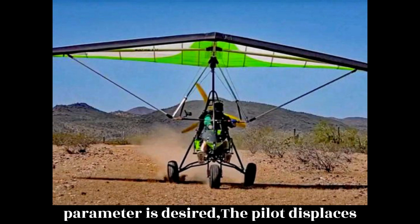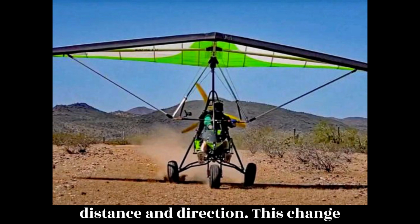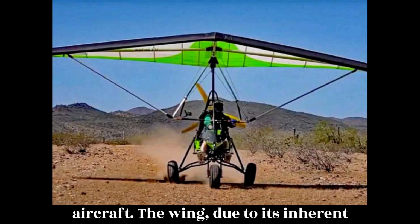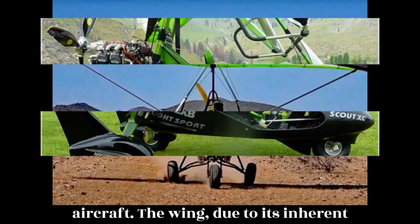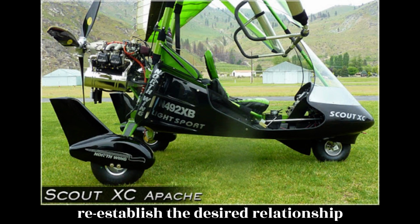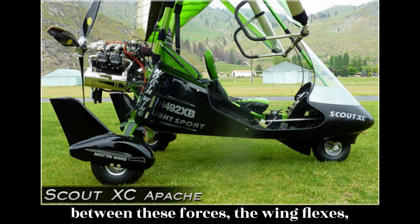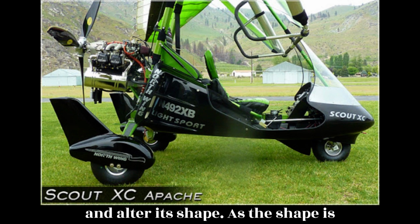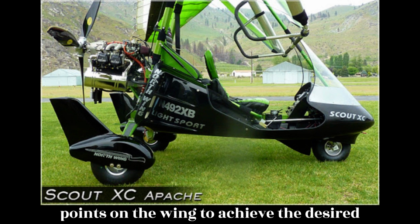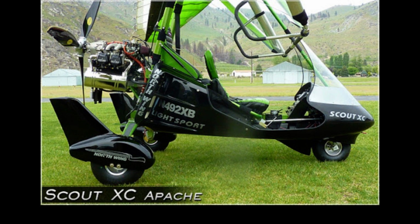When a change in flight parameter is desired, the pilot displaces the aircraft's weight by the appropriate distance and direction. This change momentarily disrupts the equilibrium between the four forces acting on the aircraft. The wing, due to its inherent stability, then moves appropriately to re-establish the desired relationship between these forces. The wing flexes and alters its shape. As the shape is changed, lift is varied at different points on the wing to achieve the desired flight parameters. End of page 1-5.